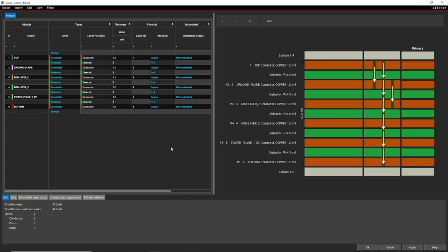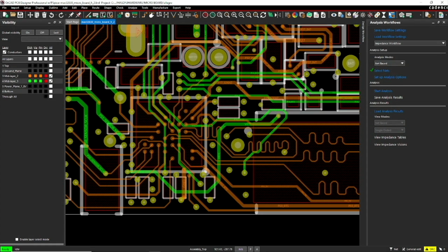But I want you to notice something with that being said. We understand that using planes adjacent to traces helps to shield other traces from EM waves. However, there is no such protection between layers 3 and 4. These are both signal layers carrying high-speed signals. So does that mean we might have a problem for layer 4 signals underneath layer 3?